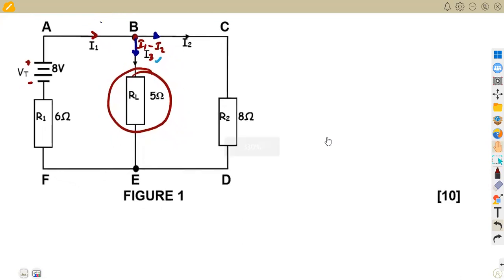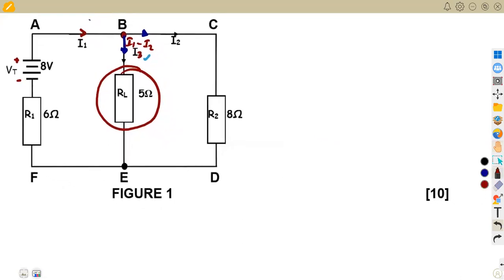All right, so the first loop that you're going to take, like I said, is a question of your choice. You play around the way that you want. As for me, I'm going to consider my first loop from this voltage source of 8 volts, and I don't want to work with the negative, so the direction must be from the positive. I'm going to take it from the positive in this way, so that I avoid working with negatives. So this is going to be my loop 1.